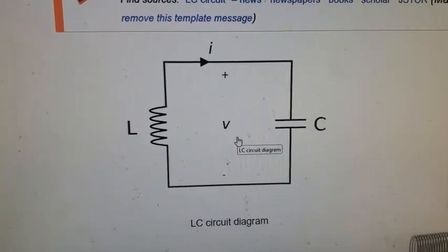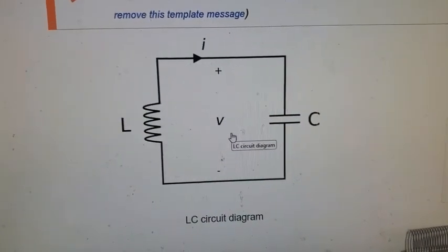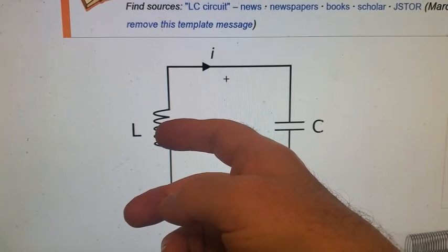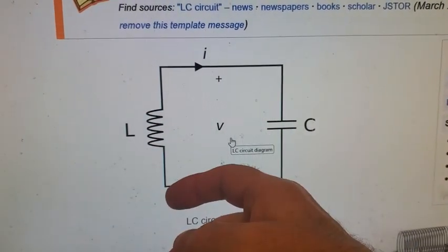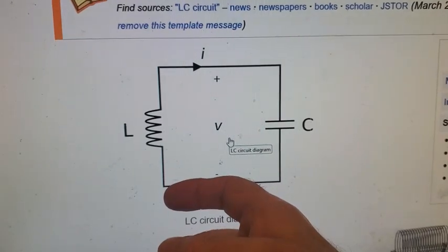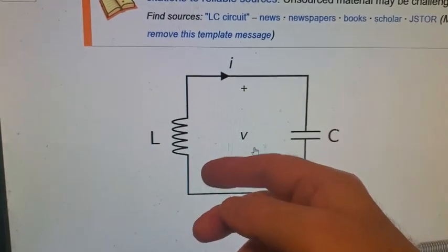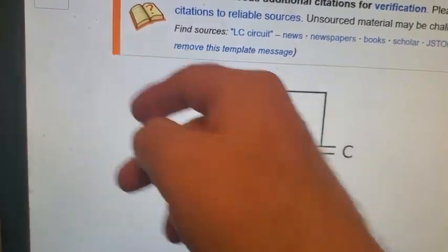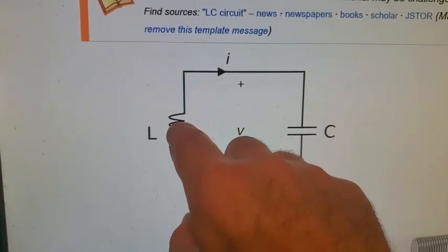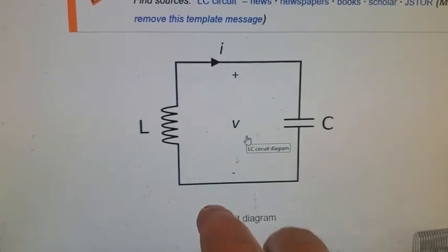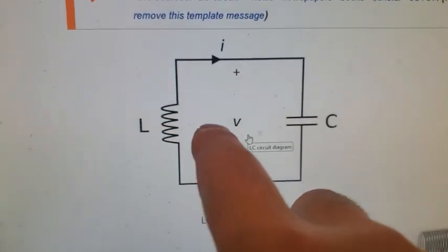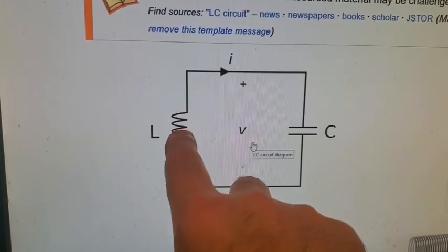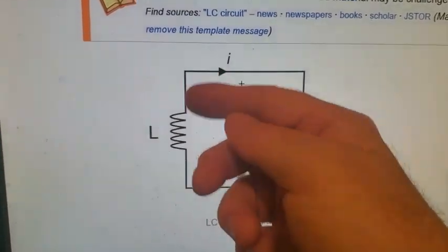Now the other question I have, which I'm less certain whether I'll make any progress on, is this. Here we're talking about the collapse of the magnetic field when it's going down, and you get this inverting DC-DC conversion where now you have negative showing up in either another cap or in this cap. That's from the magnetic field decreasing in strength. Is there a way, especially if you're using synchronous rectification, to also capture what's going on when the field strength is strengthening? That's the magnetic field changing too.